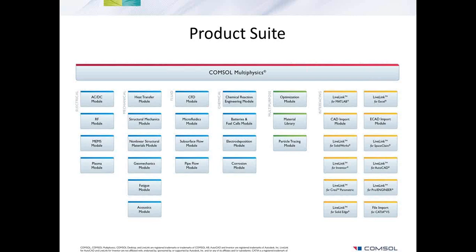Okay, so now we have a question here from Lauren, and she would like to know that we showed examples where the input was voltage, but can we model devices where the input is a load? Yes, and that takes me back to one of the examples that I discussed in a little detail. That was the flow sensor. In that case, the input was actually a load, the fluid pressure acting on the piezoelectric sensor attached to the PDMS structure. That's a load acting on the structure, and that generated the voltage, which we measured using an electrical circuit model that we attached to the finite element model.